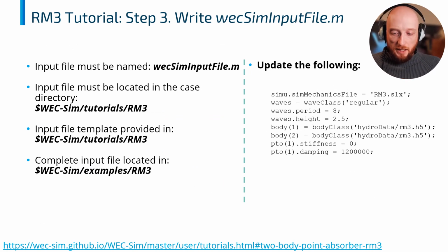So here now we're going to write the WEC Sim input file. You can open up this .m file from the folder. You should see quite a lot of information that's already there, but it's incomplete. So the idea of the tutorials is that we've left out some information for you to complete them yourself. If you do want to cheat and just get to the end, you could look at the same model in the examples folder, and that one should have everything that you need and it will just run.